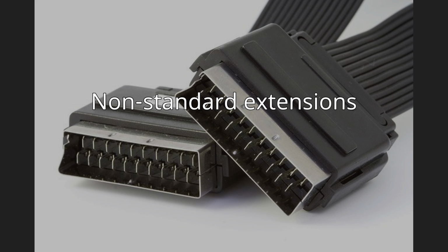Some of the most creative usages appeared in analog satellite receivers. The function of decoding hybrid, time-compressed analog-digital MAC transmissions into RGB and analog audio was one example. The D2B pins 10 and 12 were used for communicating with satellite dish positioners and for driving magnetic polarizers, before these became incorporated into the LNB. The daisy chaining features were used to connect both a pay TV decoder and a dish positioner/polarizer to a single decoder socket on the receiver.